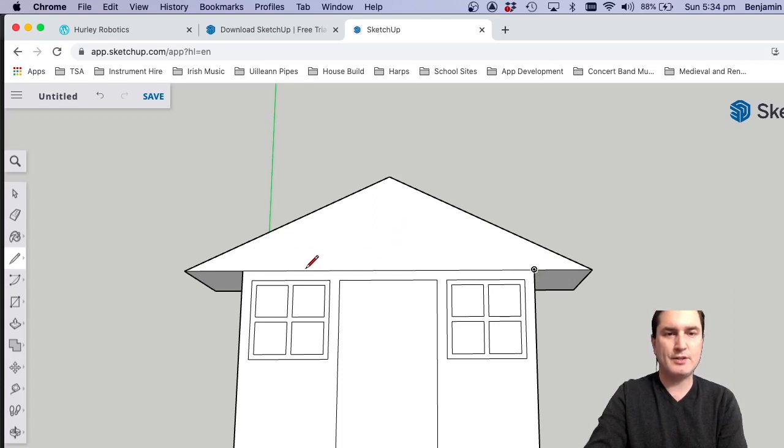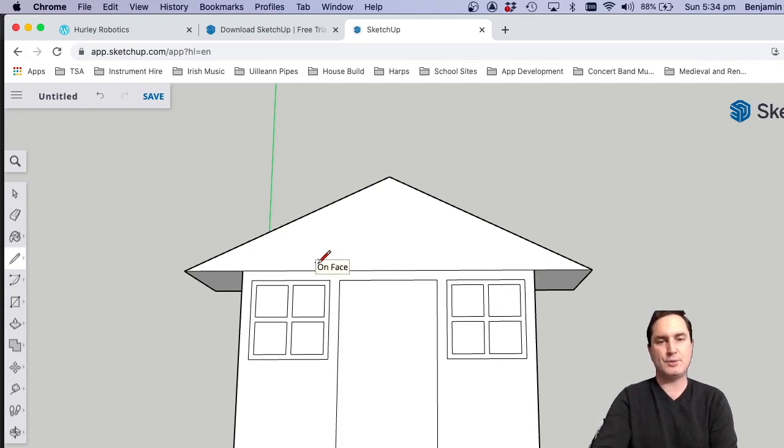Now you might be thinking, why didn't I just leave that line there when I pushed the original flat drawing up? If I had done that, that would have created two things next to each other, not one solid 3D object. It would have had a break in the middle, and that's going to create problems with 3D printing. At best, it's going to have two separate things next to each other that aren't going to print well. It's going to try and print two separate things that might snap apart. It's not going to be strong, or at worst, it might make an error and might not want to print it at all. So we always want to extrude one object on one surface and then make alterations on other layers if you want to do other things on other levels.